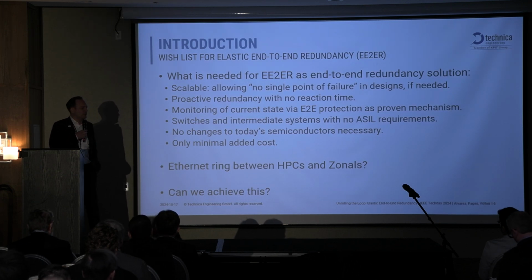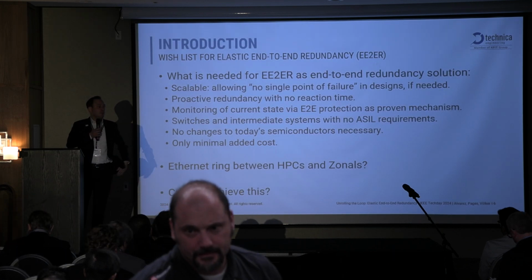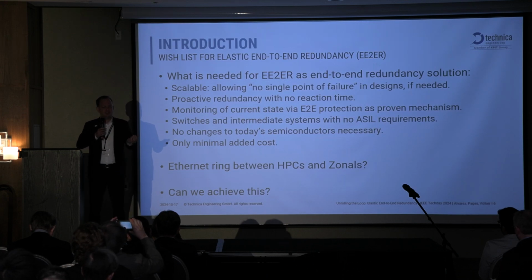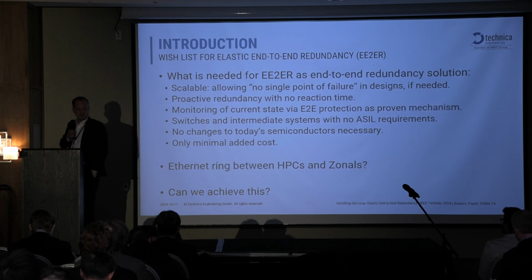And we think for saving money, of course, it also makes sense that we don't have any ASIL requirements on intermediate systems, more specifically on switches. Do I want to run ASIL D software on a switch for the redundancy if I can avoid it? I wouldn't do that. Maybe you have the same opinion, maybe a different one, but we try to avoid that. Let's see if we can do that.